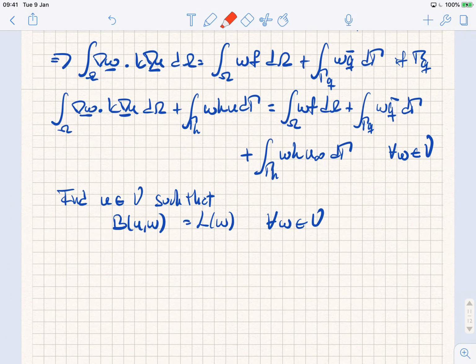Again, the same steps as we did before to get the system of linear equations do not change from this point forward. So we get the Galerkin formulation, the finite dimensional form, right? We take these U's, the temperature, and the weight function from our finite dimensional space, or our finite element space. And then we plug that into the bilinear form. We get the stiffness matrix. We plug the weight function into our linear form. We get our force vector, and everything remains the same as before. Okay?